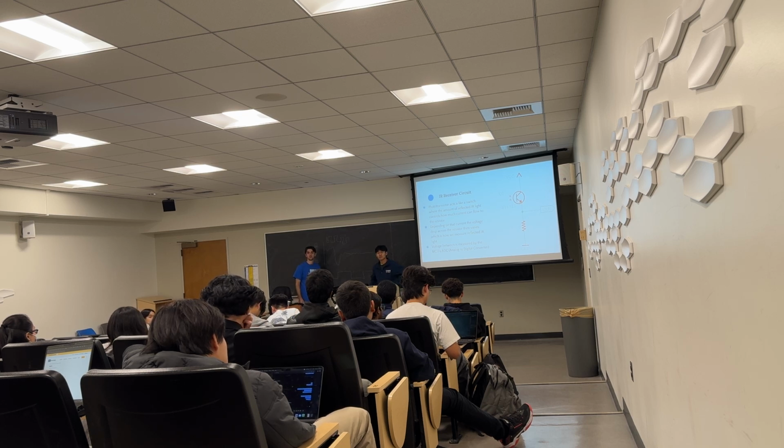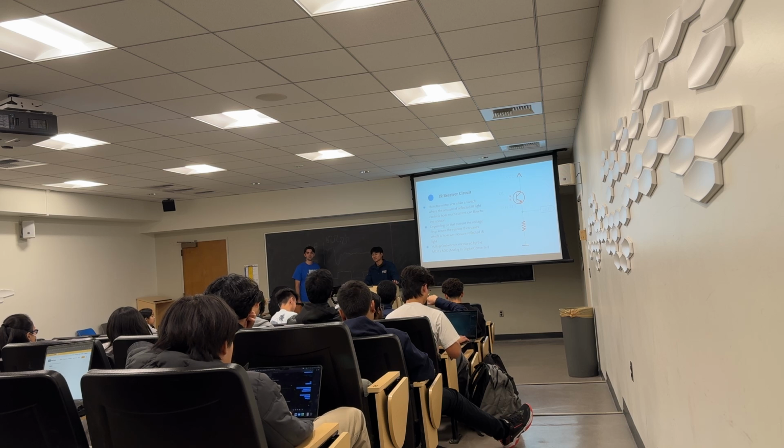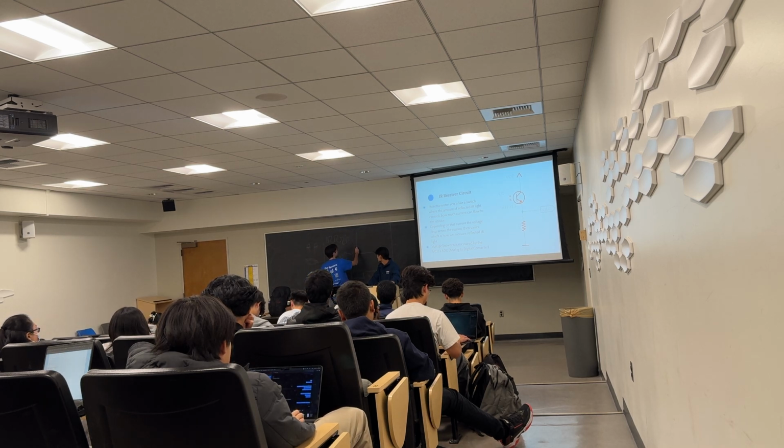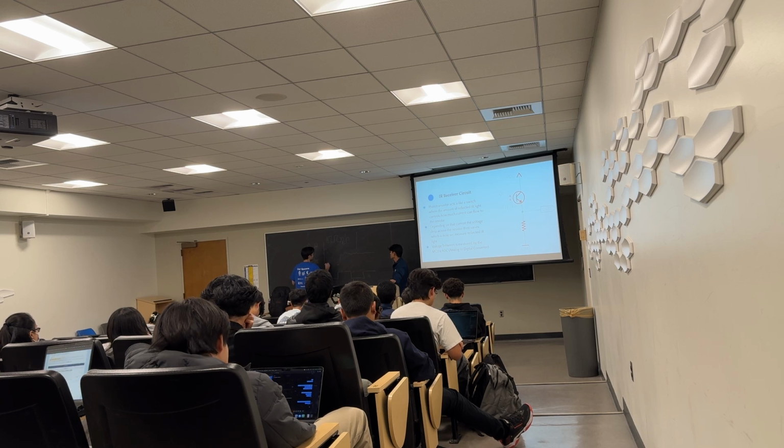Is it because the microcontroller might not be able to read the analog signals? That's exactly it. It can't read it. If you told it to read it, it would basically just say this is on. It's like what I was saying with Arduino. Let's imagine this was low at the start but varying, and then you take it out into the sun, it would just read like this.